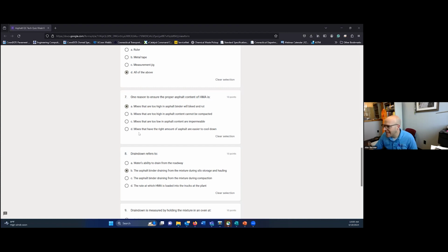Question D says mixes that have the right amount of asphalt are easier to cool down. We're not putting in enough asphalt to impart any type of change regarding the specific heat or how much heat retention our pavement has. So the correct answer is A.